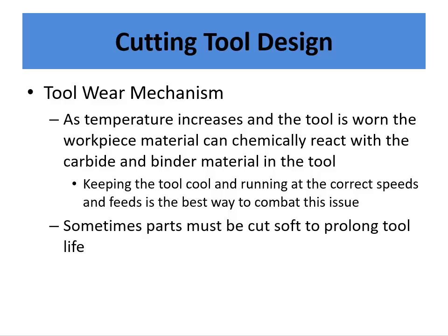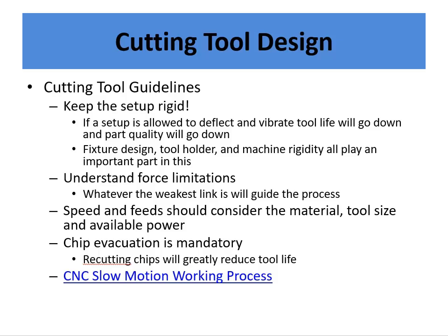In general, I would say the tooling cost as a fraction of the entire project is probably small enough that nowadays with modern tooling, you'd want to just cut parts hard, actually. But it is a strategy that's available. So ultimately, you need to keep your setup rigid.